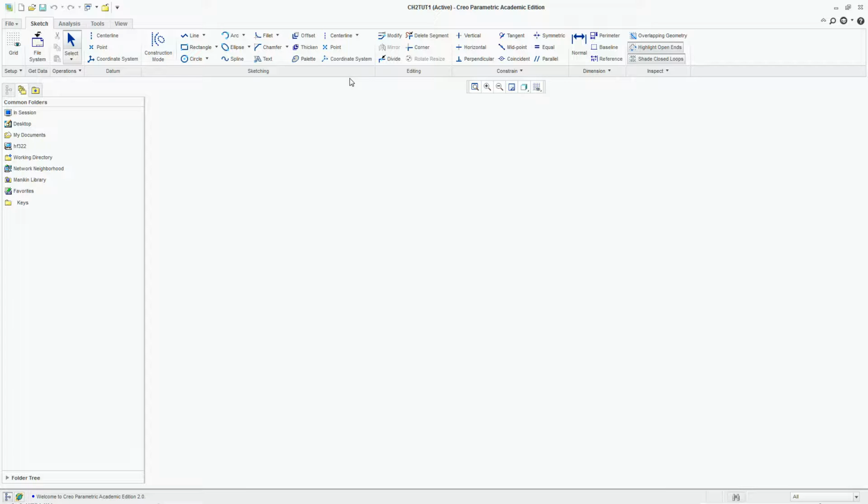Now I'm strictly in the sketching environment. I can't actually make 3D models from this mode. I'm just creating basic sketches. So the rule of thumb that I want to use every single time that I create a basic sketch is to just draw either my first line or my first two lines or a circle or something, just so that I can get my scale represented very well before I go any further with the object.